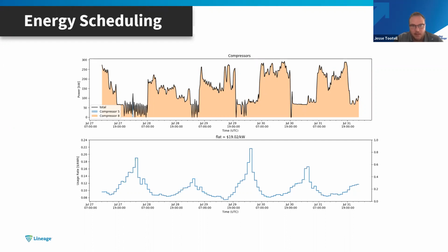You can see we're dropping load. This is the earliest example. This happened in 2018. Dropping load when the prices are increasing, increasing load when the prices are dropping. And this is also a demand mitigation effort, because we don't want to spike a new demand charge as we recover from those low periods. And so it's a bit of shedding and shifting. Next slide, please.